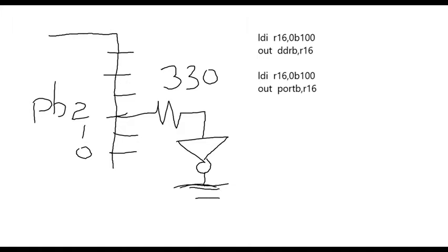Now suppose you want to turn off the LED, which you can do, certainly. And what you'll do is you have to load R16 with a value. Let's do this in base 2. And you want to put a 0 for the LED. And then we need 2 more zeros to be the placeholders so that our 0, this one right here, is in position number 3. And then finally you have to send this out to port B. So that will do it.